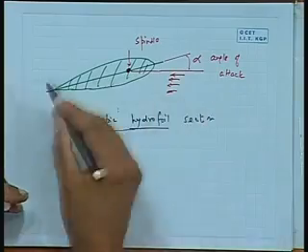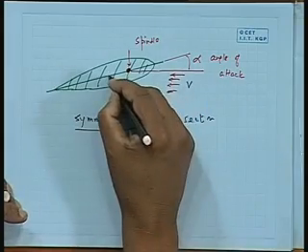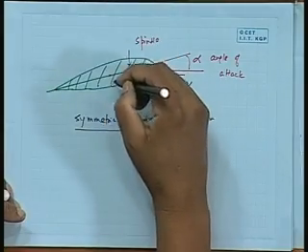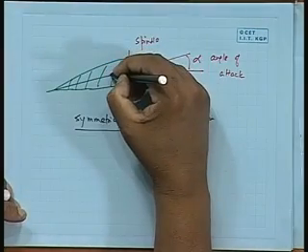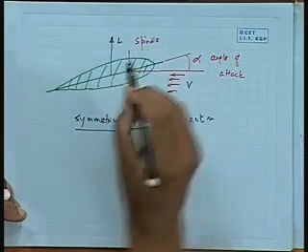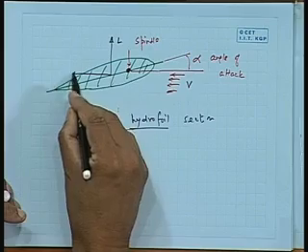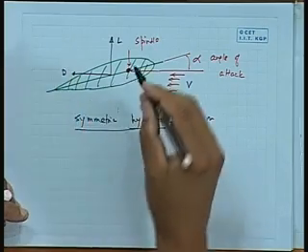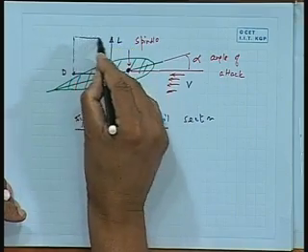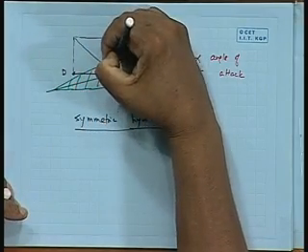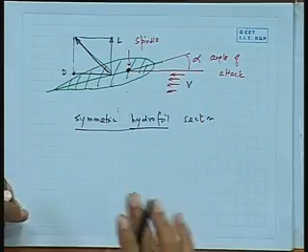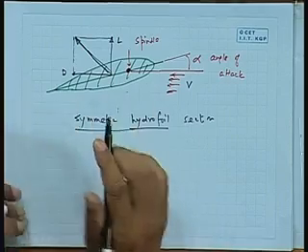Now if you have a velocity coming here, v, what happens, as you all know, is it is going to produce a force in some direction. Primarily there will be a component in this direction which is known as lift force, and there is a component in this direction which is called drag force. Okay. If I combine the two here, this will be my net force. See, by definition in an aerofoil there is a force there.